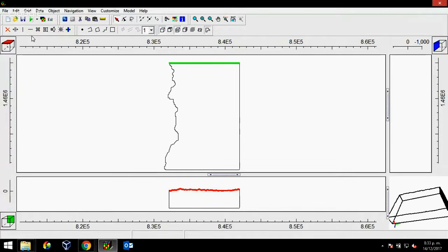Some users told us that they use a mean of the water table levels and subtract that mean from the topography to have initial heads, and then they start to calibrate the model with the water table. However, we don't have piezometers here, so we are not going to do this in this webinar. In a future webinar, we're probably going to use that to calibrate our model.